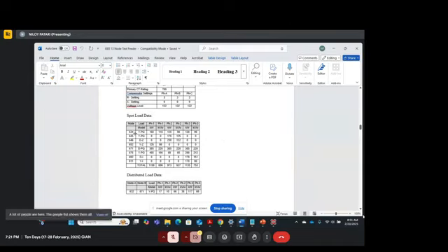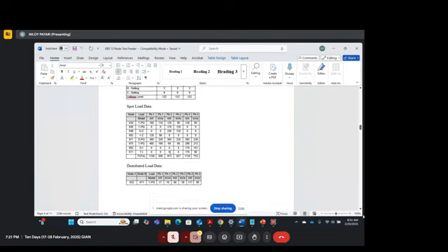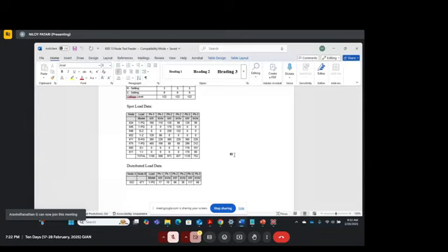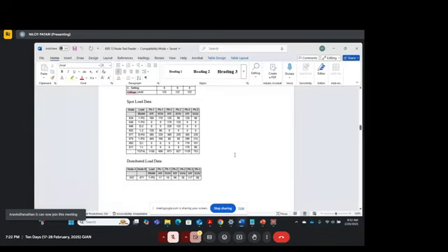Now 634 has PQ loads, in star formation, and then you have exactly the active and reactive power loads for each of the phases. So everything is defined in this particular document: which nodes are connected, how each of the nodes is connected, what is the length of the line, the configuration of each line, the configuration of regulators, transformers, and in which nodes loads are placed.